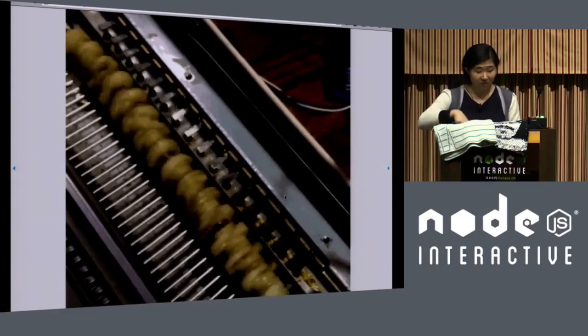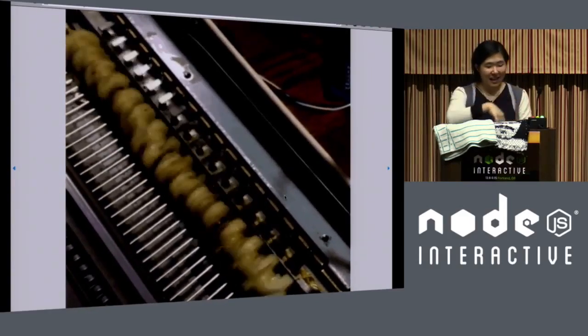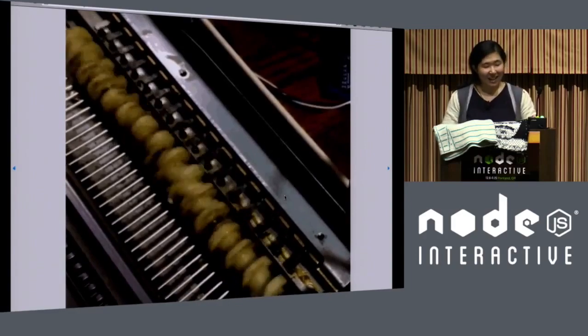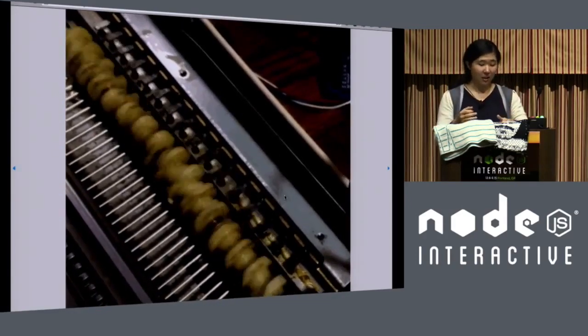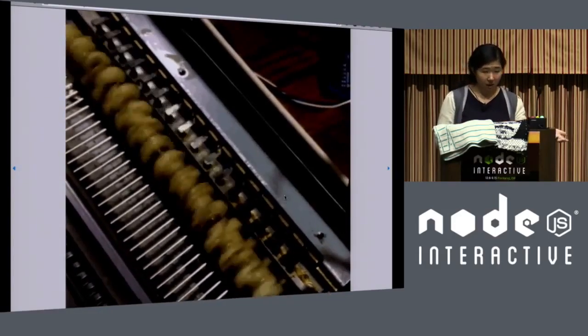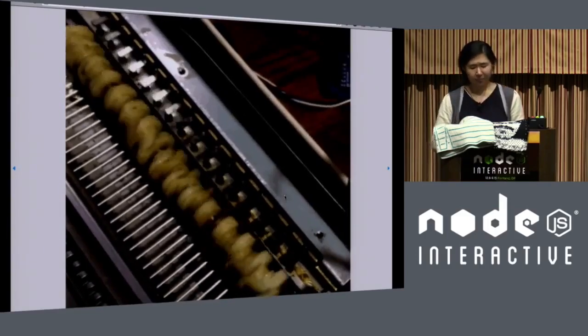From here, this white rolling thing moves a pin underneath the machine mechanically to transfer the data into that carriage, so that the machine can knit either a base color, in this case white, or the highlight color, in this case green.